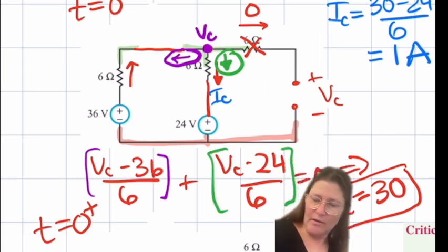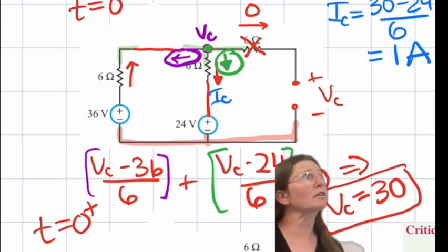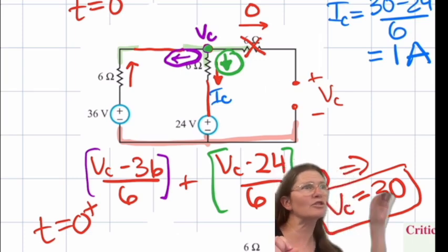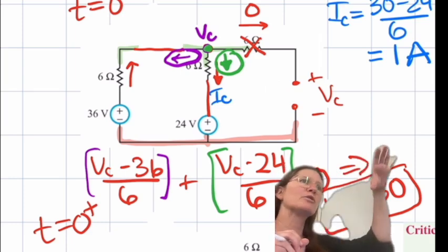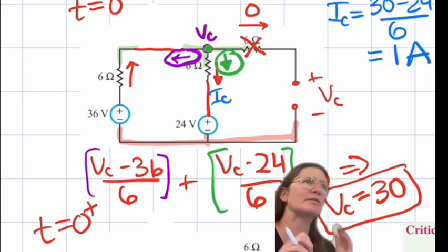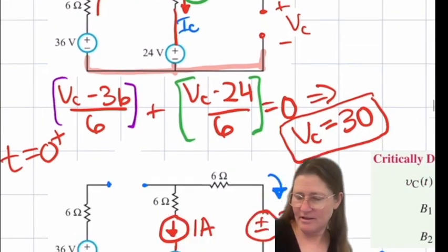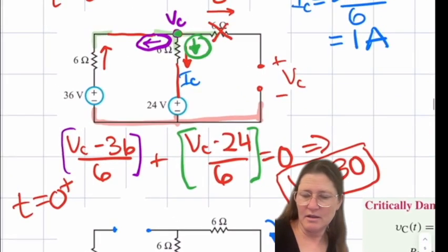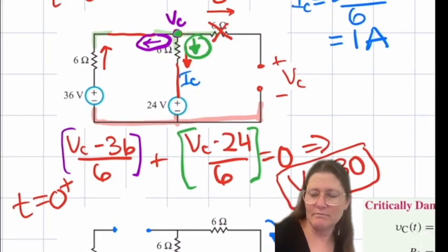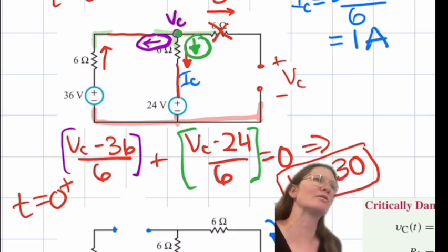is VC minus the negative side of it, which is 24. So it's just taking the voltage using Ohm's law, the voltage across the resistor divided by the resistance. That's good. Does that make sense? Yeah, and I guess we equate it to 0 because there's no current going through the open branches. Correct, yeah. So this would be plus 0 equals 0.